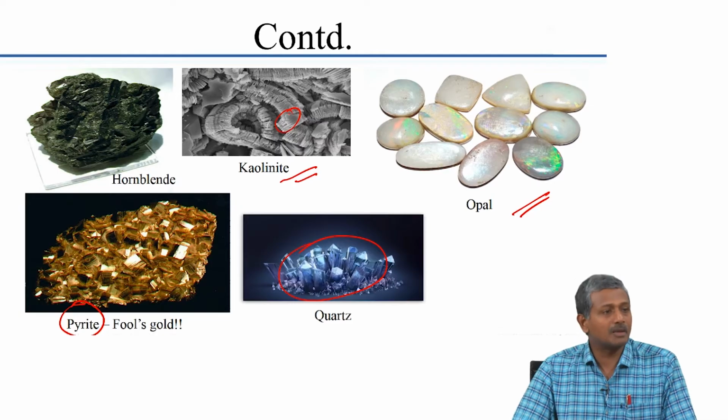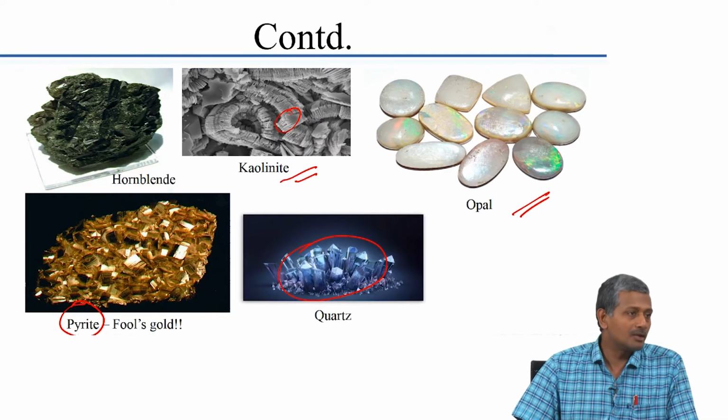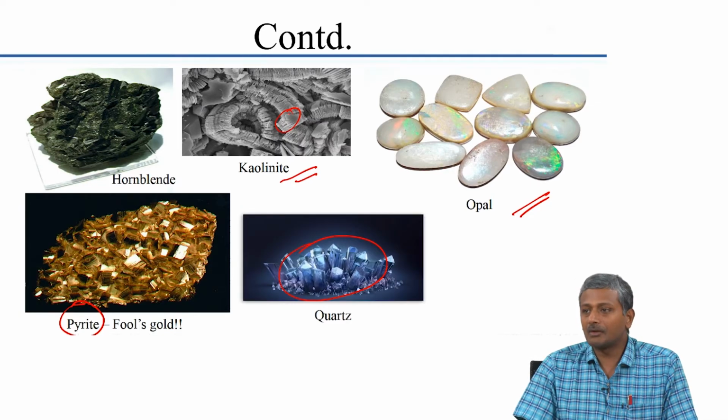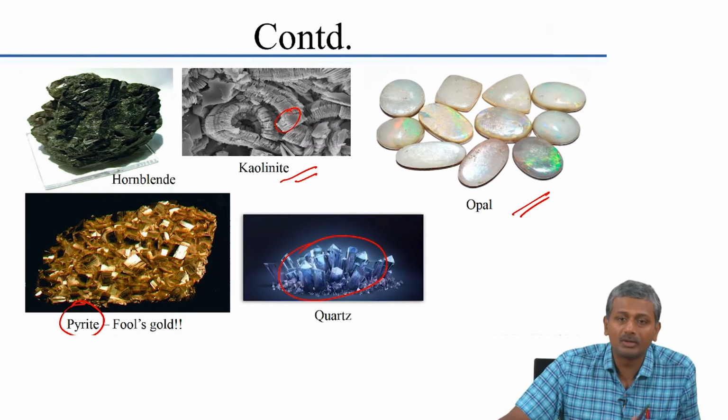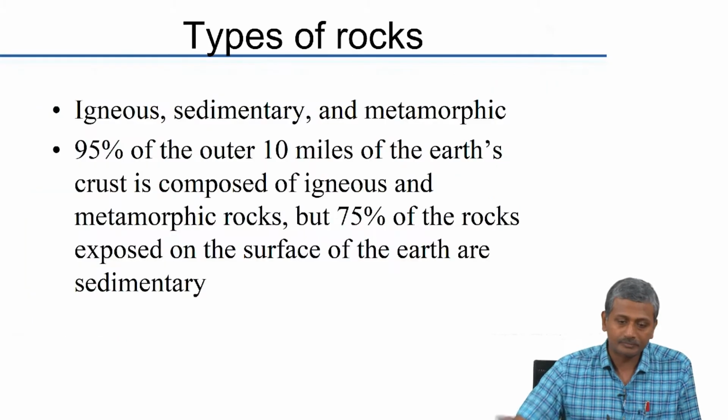So, the clay becomes activated clay or calcined clay, which is quite useful as a pozzolanic material, and you can replace up to 25-30% of your cement with calcined clay, especially the kaolinitic clays. We will talk about that in more detail in the mineral admixtures chapter.